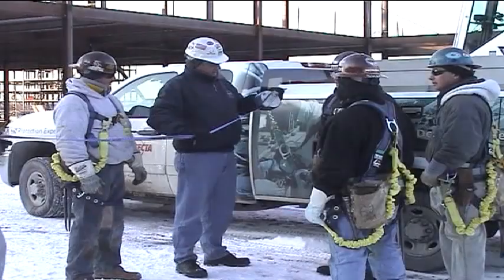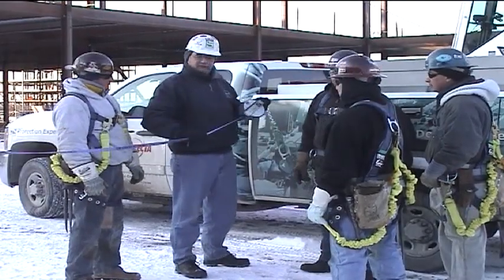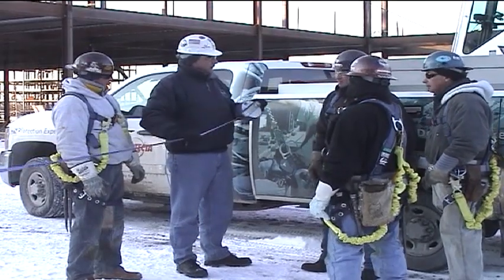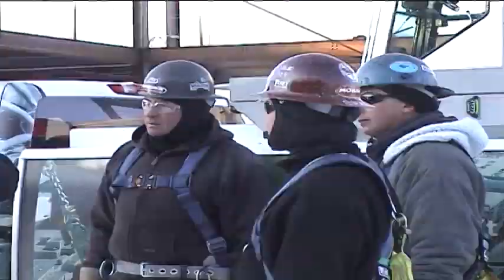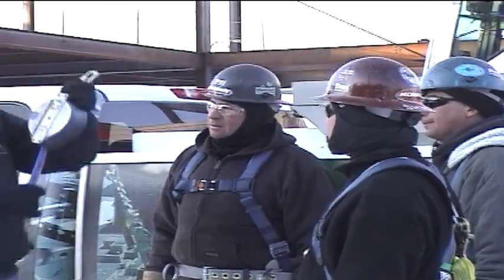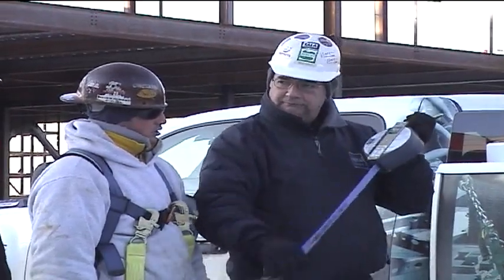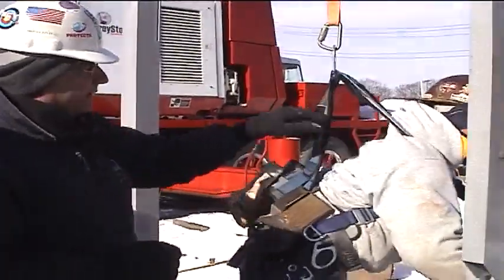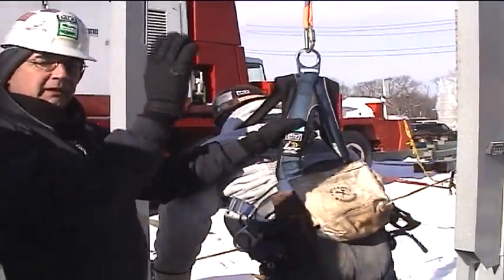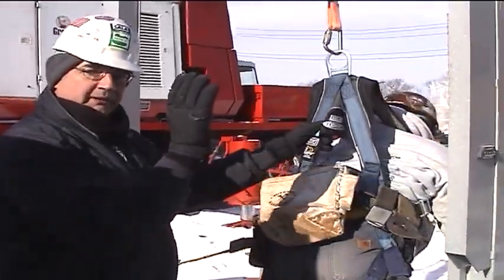An employer is required to provide fall protection training to their workers who might be exposed to fall hazards. Employees must be trained to recognize fall hazards and in procedures to follow to minimize hazards. The training must be performed by a competent person who knows the nature of fall hazards in the work area,